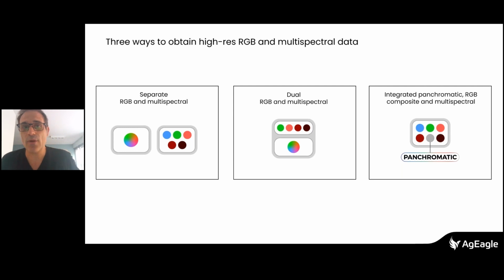Then, secondly, we have the dual RGB multispectral camera. So this is a very popular option. It used to be always in the market. To give it a name, it's the Parrot Sequoia camera. Looks exactly like this. And now as well, the Mavic multispectral from DJI has also this option with 4 multispectral bands, and in the same device, a high resolution RGB camera. And strangely enough, both have almost the same configuration, but also the same disadvantages, which are, first one, it lacks the blue band.